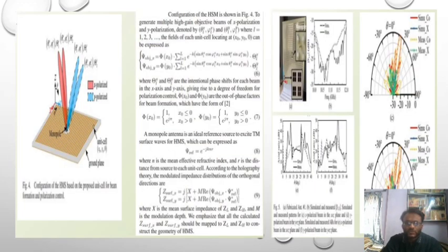As the impedance matrix changes, the propagation of the surface current on the antenna also changes, so the real part and the imaginary part of the impedance change. This makes the incident ray and the reflected ray angles differ, so I can steer the beam and maximize it in a particular direction where my user is. This RIS surface acts as a dummy version of an access point, and it can steer the beam to give interference-free communication to particular users. So the beam can be steered in that way.